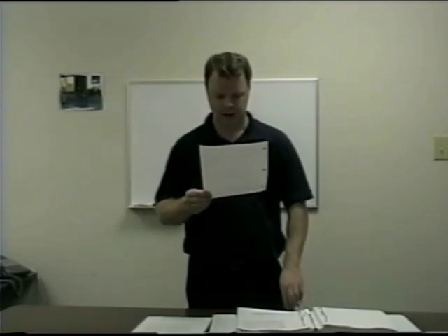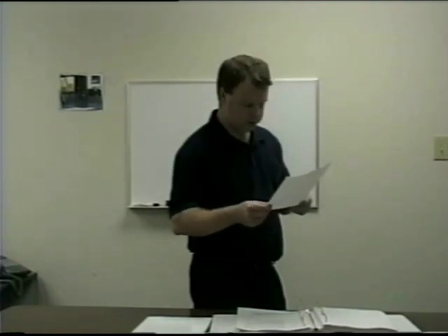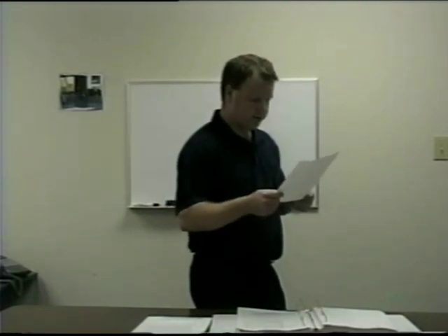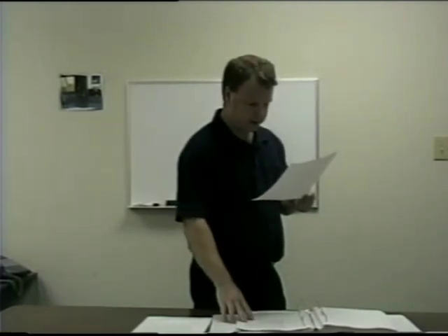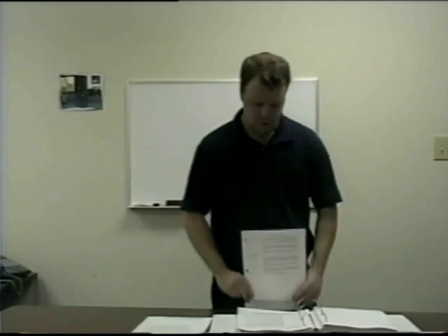Do not allow overheating. Verify delivered material is of grade and type specified, stored in the area at least 72 hours before installation and needs to acclimatize. Verify felt paper, slip sheet, or underlayment is required if provided. In this area, we're specifically concerned about that underlayment here in South Texas because of moisture warping that wooden floor.